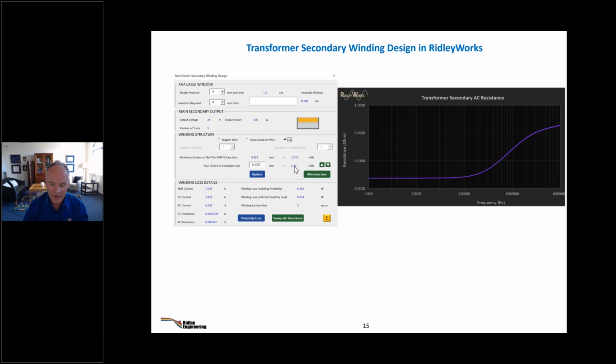Now, in terms of manufacturing, some magnetics manufacturers out there will know that working with 5mm foil is a lot easier than working with 12mm foil. So not only did you make that transformer better with the thinner foil, you made it easier to build. Less material is not so much of a factor, but being able to manipulate 12mm foil is a problem.